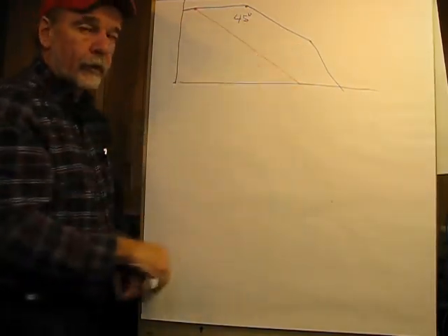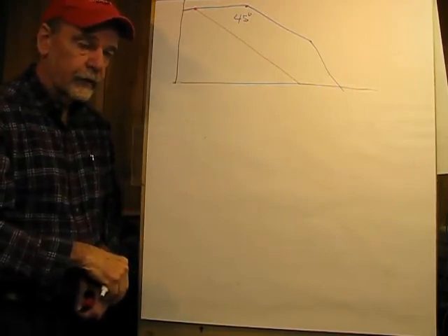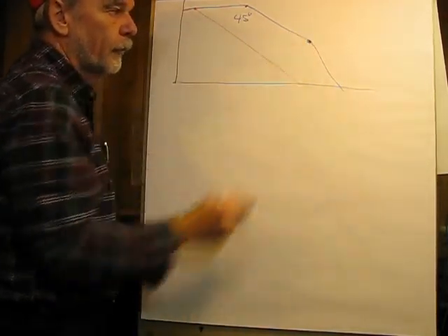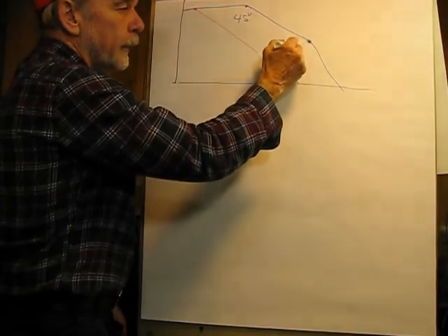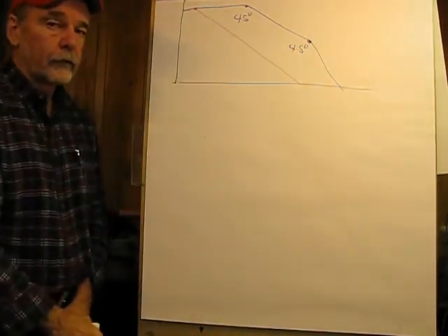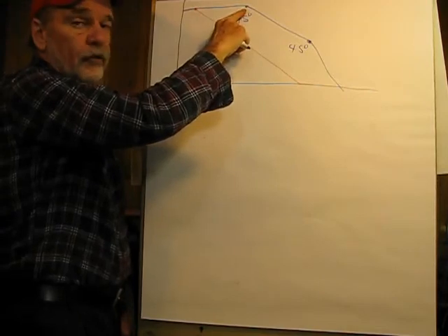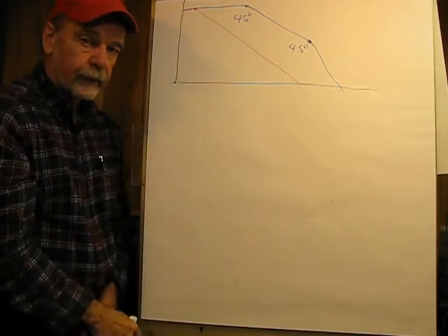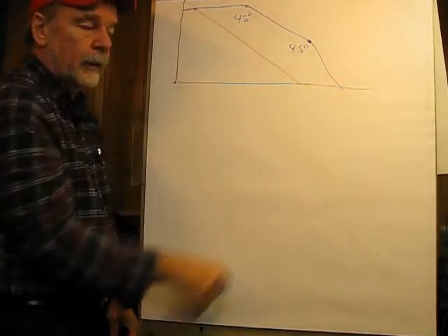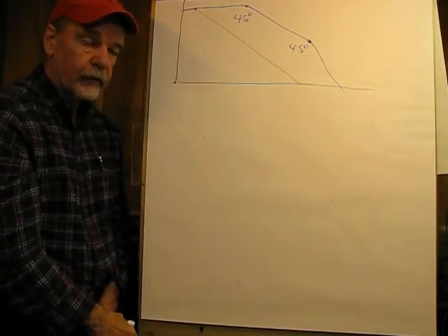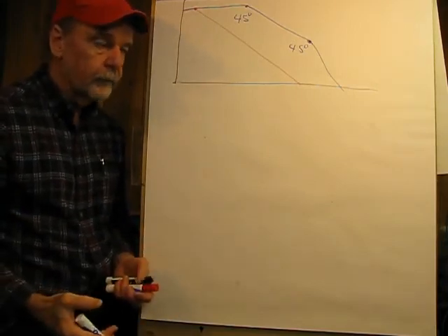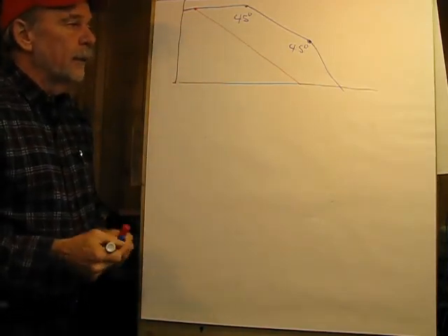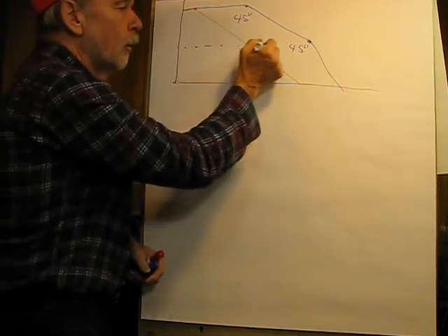Now, due to other parasitics in the integrated circuit, because the manufacturers do not strap it with an internal capacitance, we have another pole, another critical frequency out here. And its phase shift is also going to be 45 degrees. Now, as we move from this point, we're going to be approaching 90, and then we're going to be picking up another 45, eventually coming in down here, maybe at something close to 180 degrees phase shift, a real nice oscillator.